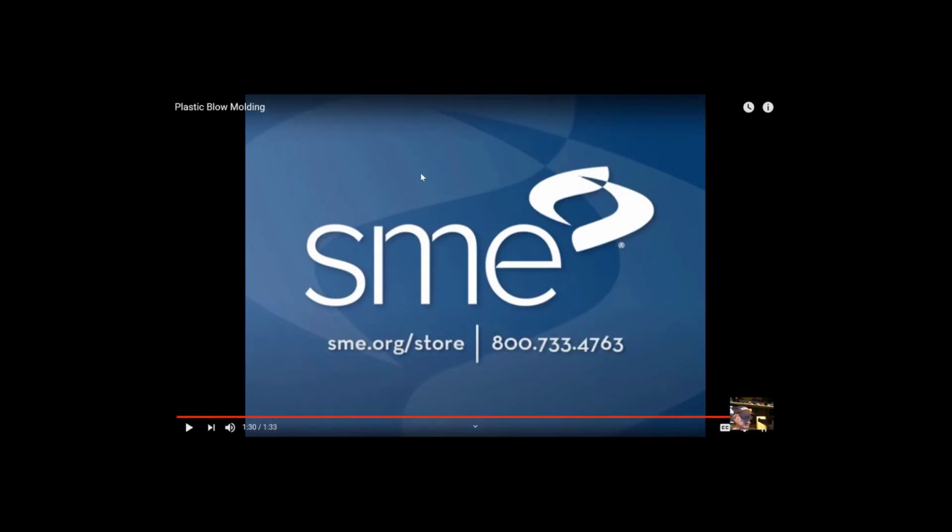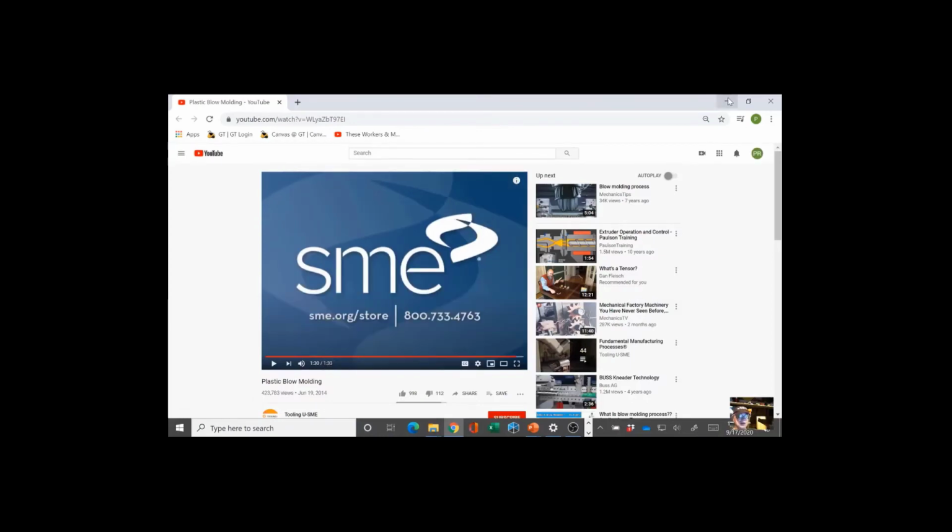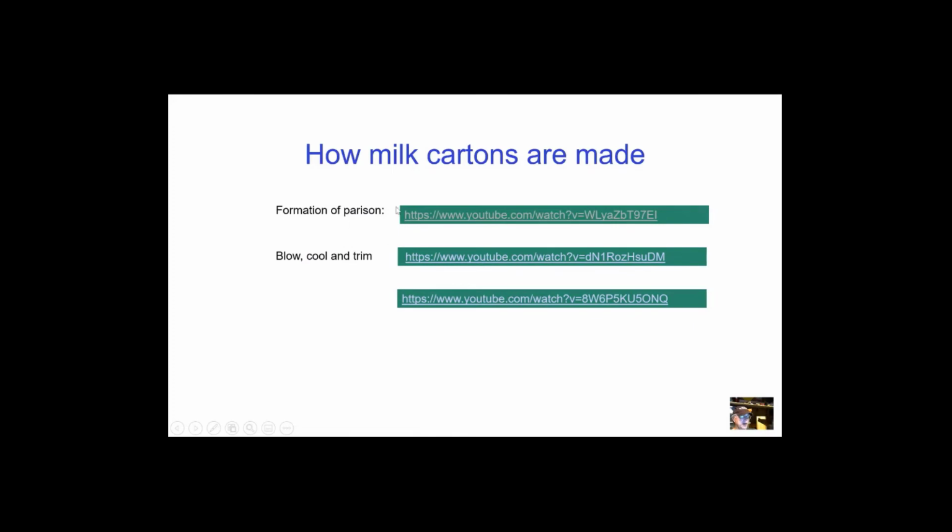So that was the formation of what's called the parison, spelled like that. And then what you do is you take that sort of oozing thin cylinder that's coming out of the hot die, and you push it into a container and seal it up, okay? And while it's hot, the polymer has to flow together, again by this process. The polymer molecules have to interdigitate by this process of reptation, okay? And at that point, then you can blow air in and shape it. So I think that will be shown here.